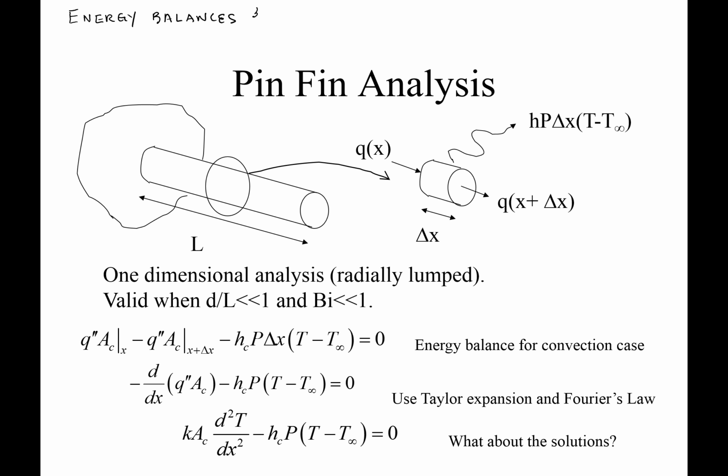And the basic rule, as we've talked about, is the amount of energy that's transferred in minus the amount of energy that's transferred out is equal to the amount of energy that we store minus the amount of energy that is generated. So some sort of generation rate. So again, in minus out is equal to storage minus generation.